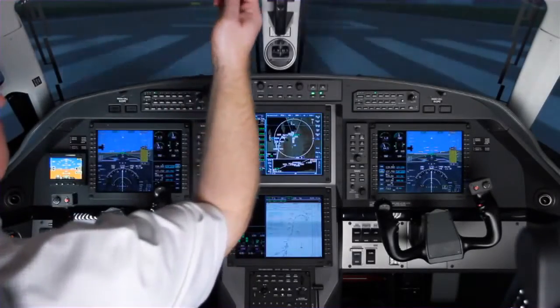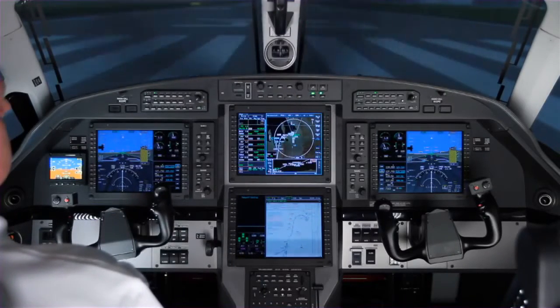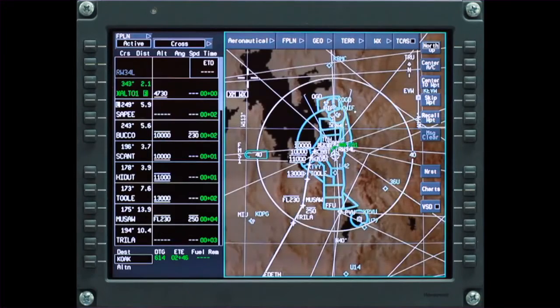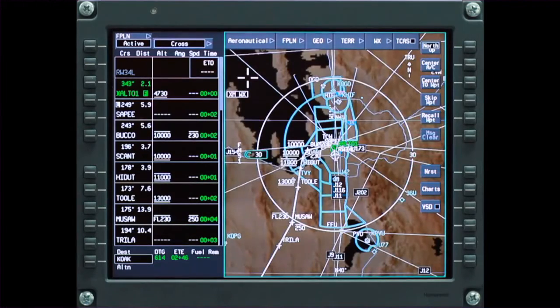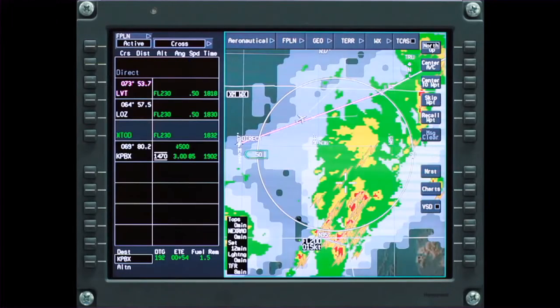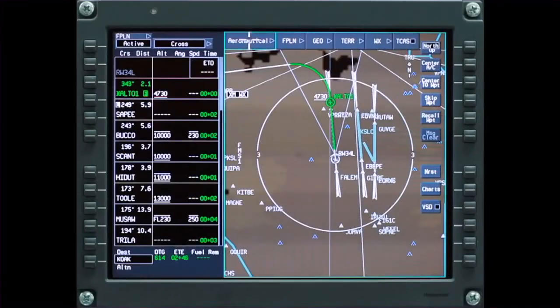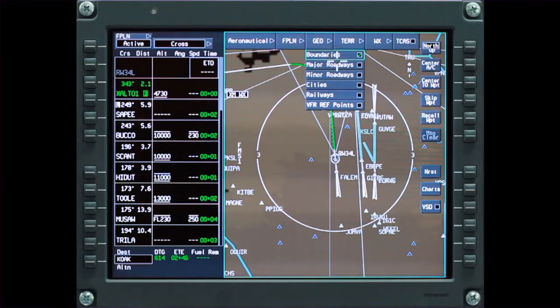The Primus Apex display system on Pilatus PC-12 NG aircraft features an interactive moving map. The Interactive Navigation, or INAV map display, is capable of showing nav aids, airways and airspace boundaries, geopolitical boundaries, flight plan information, weather information, and much more. The map display has a control bar that contains menu selections. These can be used to select the display characteristics of the map.